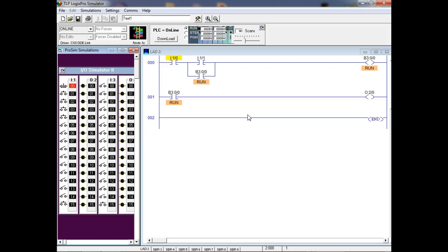On your 1000s, you're going to have to use one of your selector switches. The only thing you got here on 0, 1 through 1, these are all normally open. We do have this selector switch that I can turn on, right? You understand? It simulates a normally closed push button. In industry, you see very few of those; you see a lot of normally open buttons.